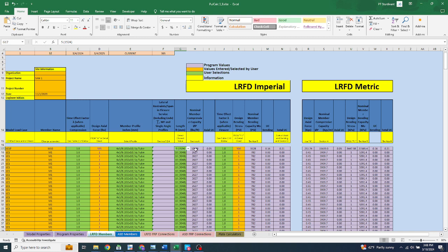Now the maximum compression under line H is now 10,509 pounds, and the allowable, not the allowable, but I still have ASD in my brain, the factored figure for bending stress is now 3128. And then over here on the far right, we have the total UC. And that's what has to happen, and that again is per ASCE 7-16. Both of these forces have to be combined to give you the total UC.